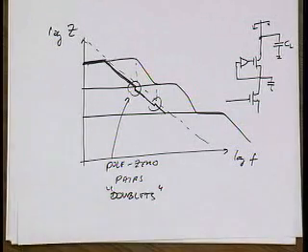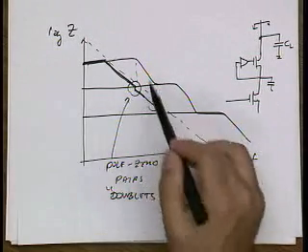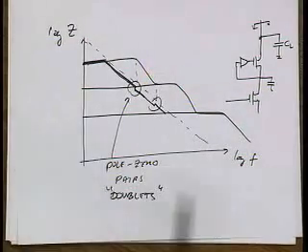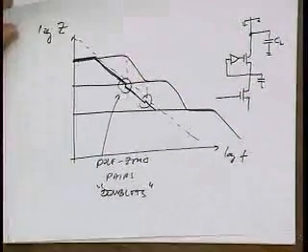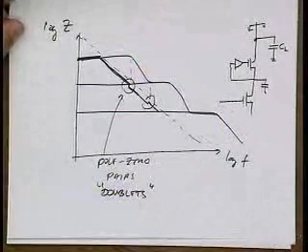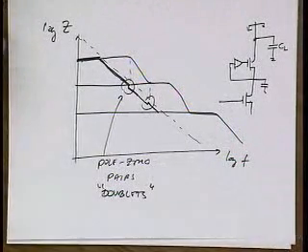And if you don't take care of them, they actually can be bad. Your settling time could actually end up being dominated by these doublets. So there's something to consider when we look at the frequency response of this amplifier. Okay? Questions?